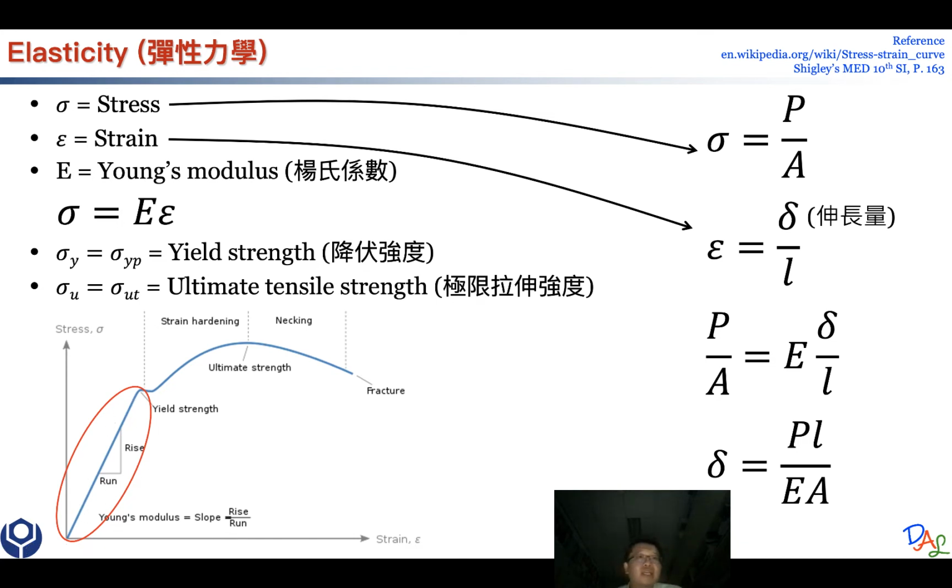Let's say you are designing a motorcycle, and you are designing in a nonlinear range. We know for metal, if a material is under a great amount of stress and is already past the yielding strength, it reaches a nonlinear region, and a great amount of deformation is generated, and it doesn't recover back to its original shape if you release the stress.